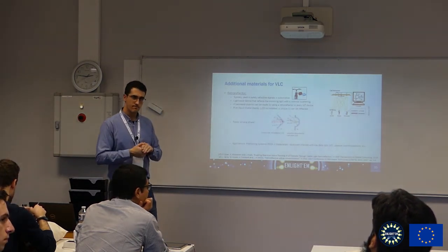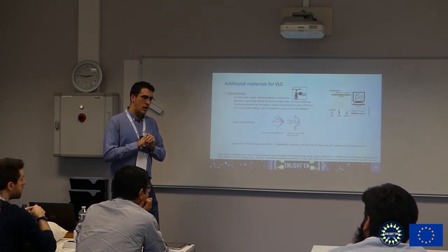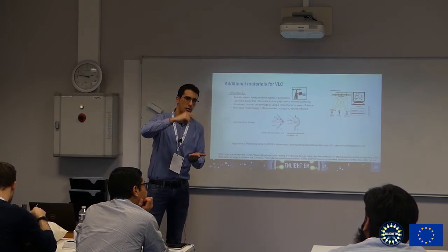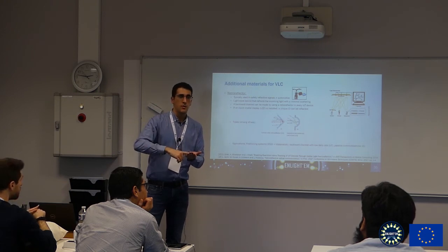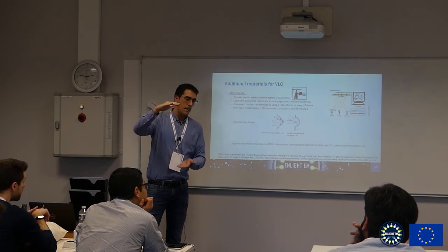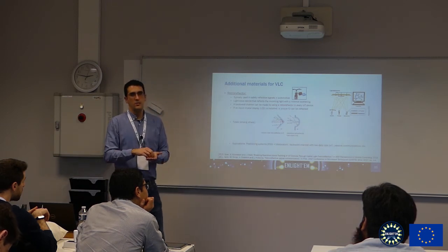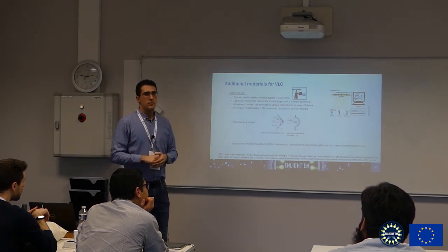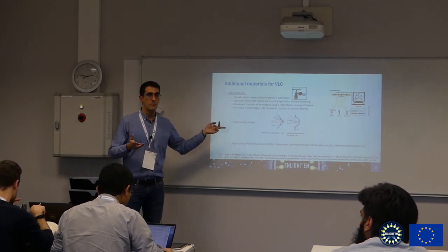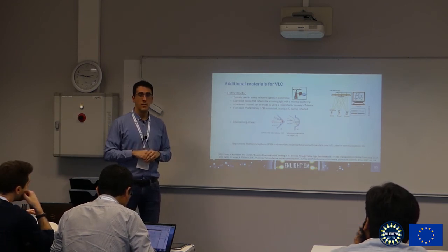Can we use the retroreflectors for non-line-of-sight VLC? It's quite difficult, because it's completely necessary to have a line of sight in order to reflect the signal in the same way. If you don't have a line of sight between the source and the receiver, of course you will receive some power at this retroreflector, but it's going to be quite difficult to get it back through the uplink. There are some ESRs working on that by using natural light. So it's going to be really interesting to see how this technology evolves.